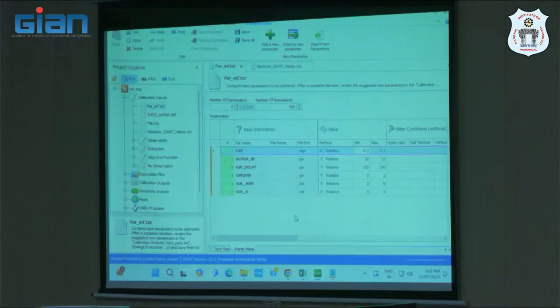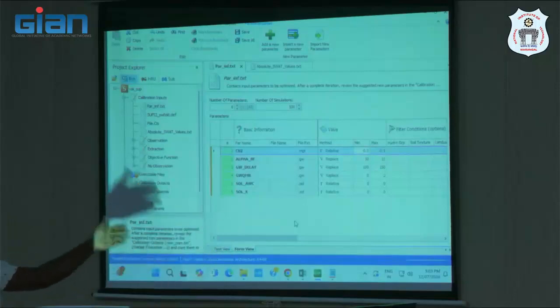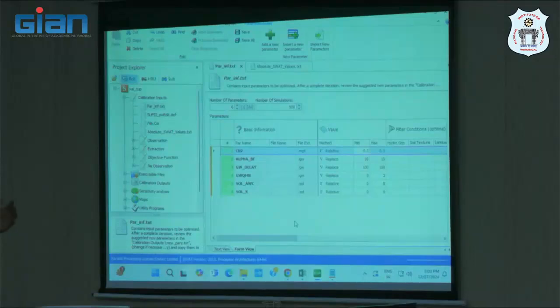If your soil hydraulic conductivity is very high, that means runoff will be less because soil has high infiltration. So you can also check the value of soil hydraulic conductivity for the model which we have run, and we need to increase that hydraulic conductivity so that our stream flow will decrease. If I want to increase hydraulic conductivity, first you should know what the initial value is. Just check.